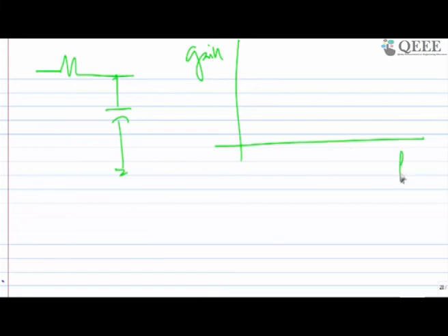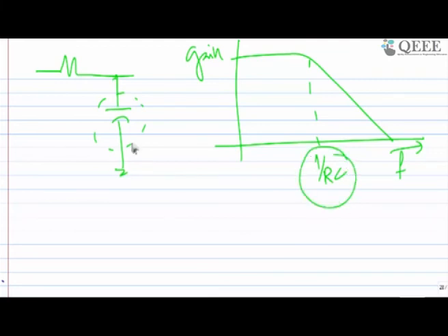Then the gain of differential amplifier will be affected when considering parasitic capacitors. Yes, it's going to be affected for sure. If you remember, when you have R and C, I'm plotting gain versus frequency. My gain versus frequency looks like this one. So you can see that because of this capacitor, my gain is getting decreased, or you can say that it creates a pole. This pole creation limits the bandwidth or limits the speed.